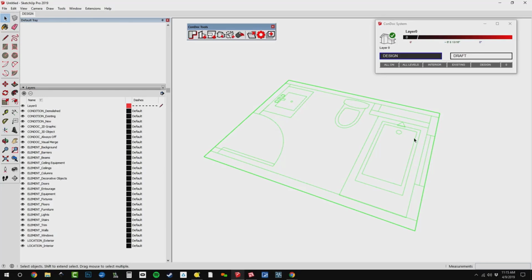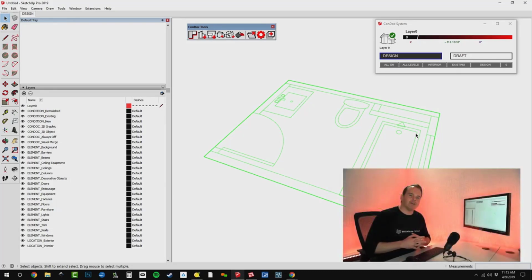So now what we're going to do is start to model this up, but one other step on importing a background drawing. Now, a background, a CAD background, a sketch background, if you have as-built field measurements, anything that you're going to model off of is a background, and that should have the background layer assigned to it, and also we can lock it. So that kind of keeps it from being shifted out of place or deleted on accident. So let's get to that.